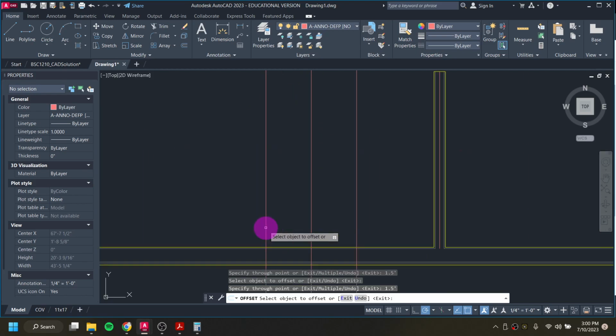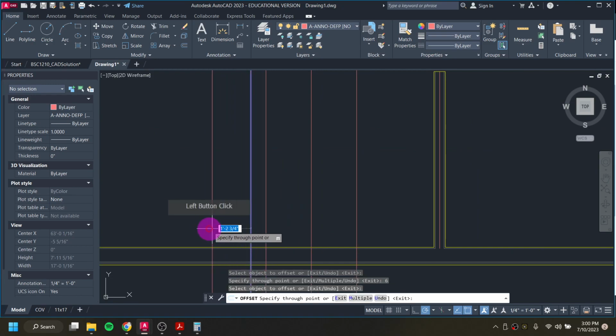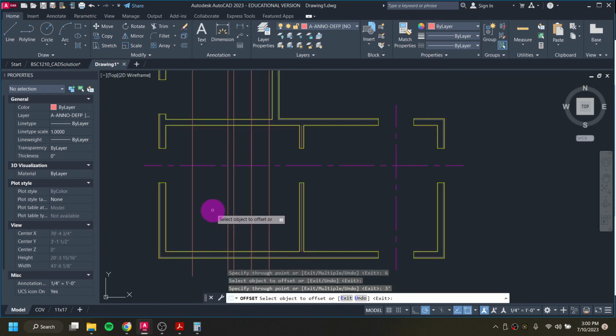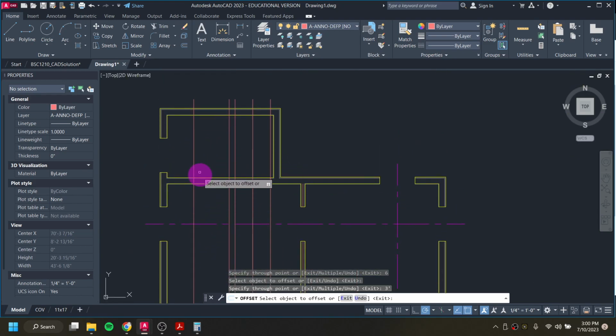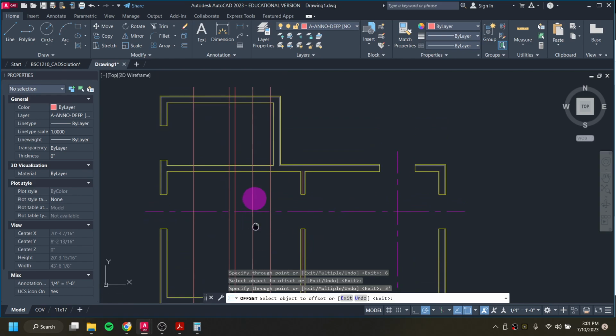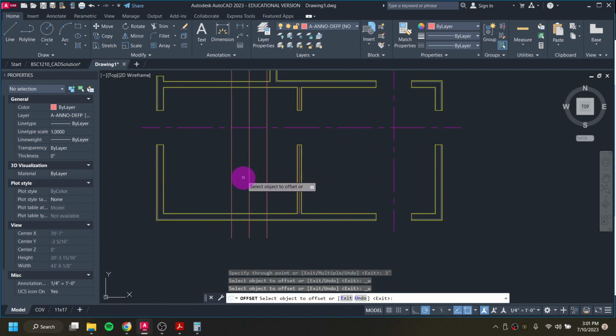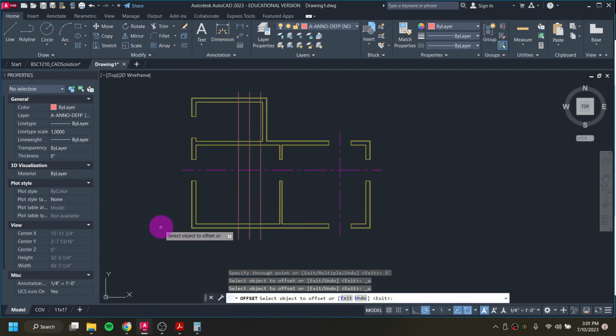What I could also do is then I could do this 6 inches over, do it 3 feet over for my window that sits here, but then I have a lot more extra trimming to do over here. So that's why I'm just going to Control Z, and not do those, because they're just going to be a little bit of a pain in the butt. So I'll hit escape to end the command.